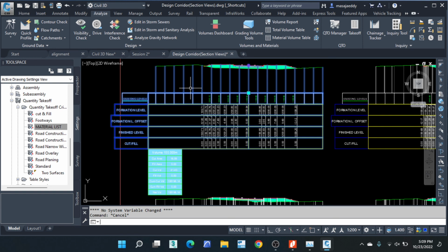You select the alignments. Then we can choose the alignment increment to chainage report. This is the one they usually use on site. I right click on it and I press execute. Then I select my alignments which I want to create my data. So I want to select the main alignment for Mitiana, the Mitiana road. Then let's say I'm going to have increments of 10 meters.